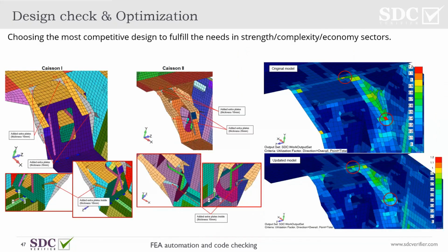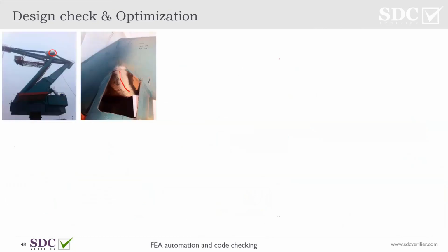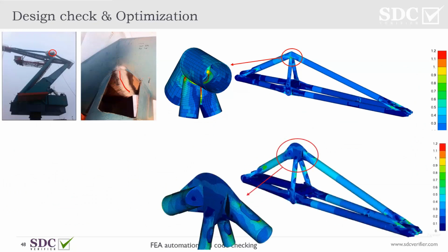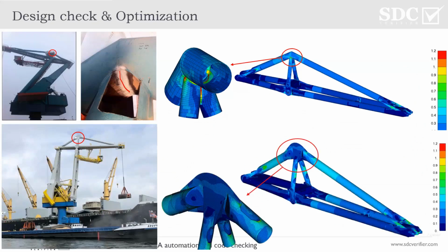Well, a nice example is shown here for one of the overhead cranes. It turned out that in the connection between the seal beam and the bridge, we've got a locally high fatigue damage level, and with the help of the local reinforcements shown around here, we've managed to avoid that and extend the fatigue lifetime for a certain number of years. Of course you can do a global optimization when simple local additional reinforcements are not enough, but the idea is that avoiding these things and extending our lifetime is of course possible.